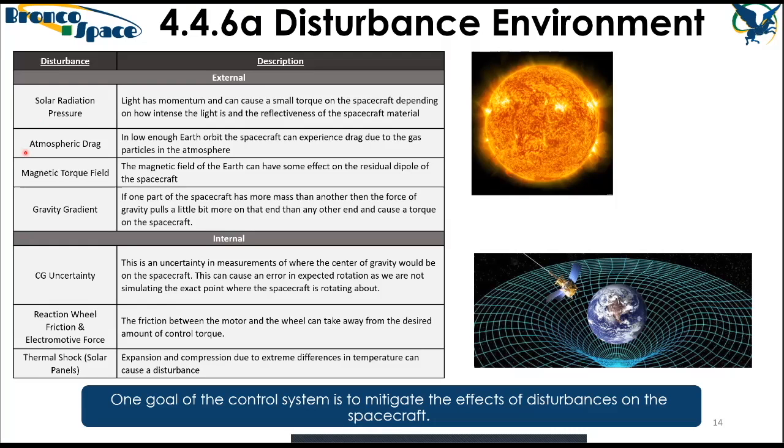Atmospheric drag just kind of is a drag. It can sometimes be used as a control method, particularly to orient your spacecraft in what's known as the ram direction, but using atmospheric drag is usually not something that is designed for because it's highly inconsistent once you're in orbit. At the incredible altitudes of space, atmospheric drag is entirely dependent on solar activity. When the sun hits the earth more vigorously, the atmosphere expands and creates more drag. Right now, we're in a legendary solar minimum, so there's very little atmospheric drag to work with.